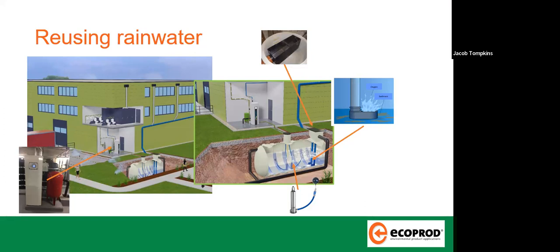There are a whole range of rainwater systems that you can use depending on roof space, the needs of the business, and how much water there is. In order to engineer the tank, we have partners who can size the tank depending on your roof space and your use. There are also pumps. There are also things called first flush systems, which make sure that all of the debris on your roof doesn't clog the tank, which reduces maintenance.